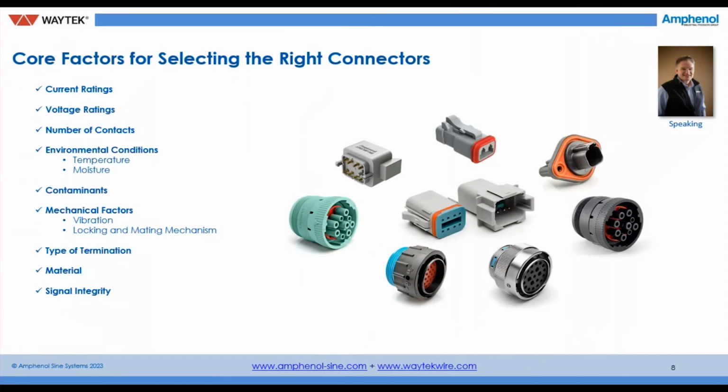Continuing on, core factors for selecting the right connectors: current ratings or current density, and voltage ratings, which is your operating voltage, will determine other parameters, other inputs such as your wire size and the number of contacts. This will contribute to the connector size and contact engagement force. Environmental conditions such as temperature and moisture must be considered. Contaminants such as brake fluids and antifreeze could be present.